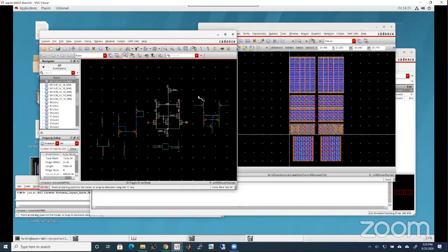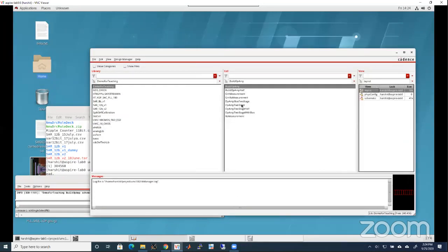Then this becomes the first stage here. And similarly, you can do the second stage. The output comes out from here, it goes to the second stage. It can be built like that. Overall, if I have to build this whole op amp and do a proper layout, it takes roughly 6 to 8 hours to really get this done with LVS and DRC clean. Okay. So now I will show the LVS flow for the op amp that we have already built.